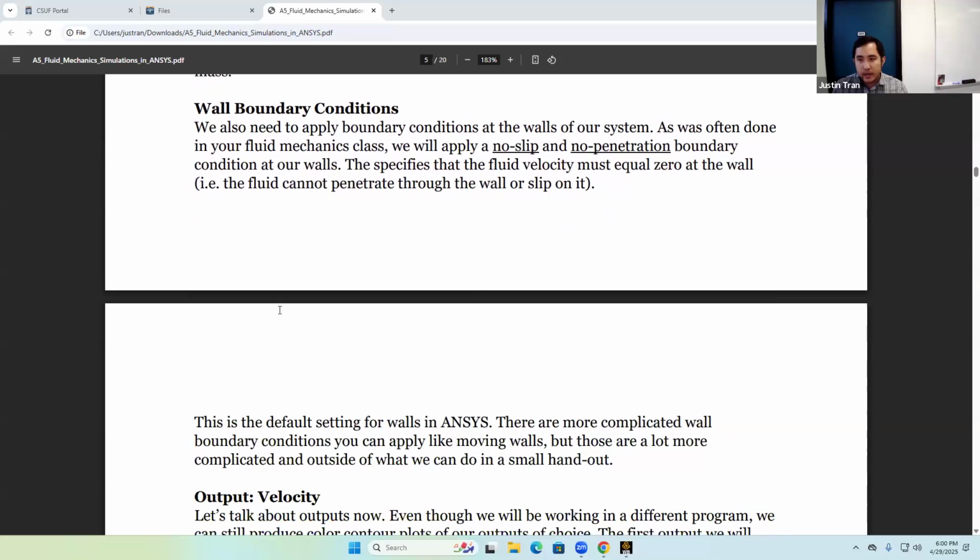All right, so whenever you're running a CFD simulation, it's really important to identify the wall so you can apply that no slip boundary condition. And you're going to see in the example that a big part of defining our geometry is to actually define that wall. Okay. So that was a speed run through just the setup for CFD. Obviously, there's a lot more that we could talk about, a lot more concepts with fluid, but I think that's at least enough to get you started.